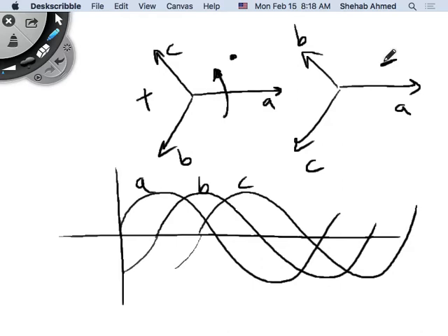The ratio of the bases is equal to the ratio of the terminal voltages. If you do that, you still eliminate the turns ratio that's in the single phase equivalent circuit, and I will show what that means. But the phase shift will still be there.